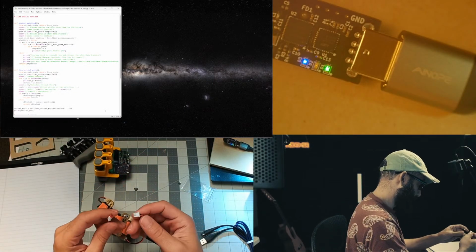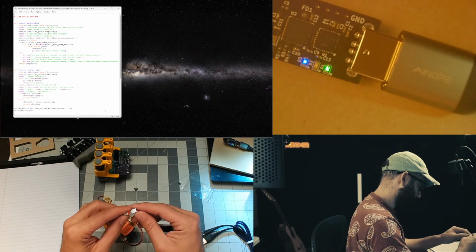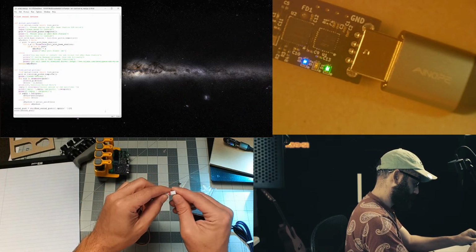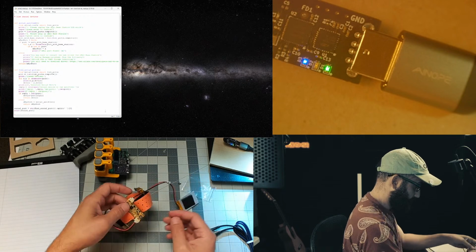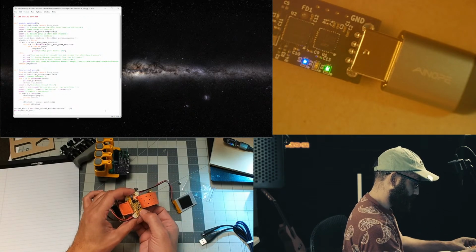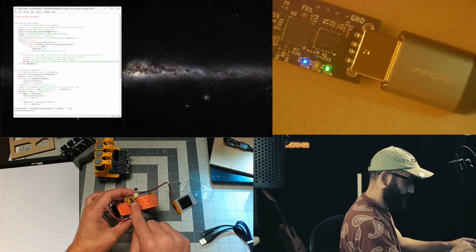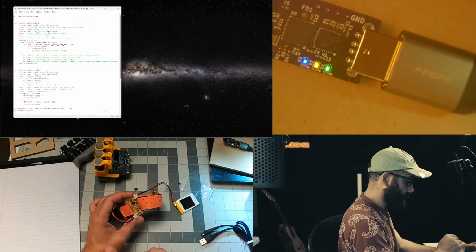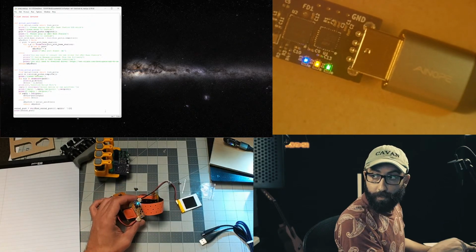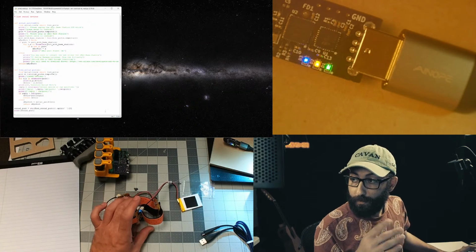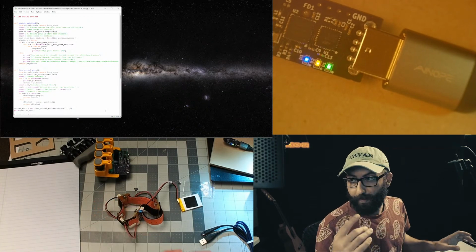So I'm going to plug in one of these uMyos, like so. And I'm just going to turn on this first one. It turns red and flashes green, and green means that it's in the USB receiver mode, and we do see that the D2 light lights up on the base station.